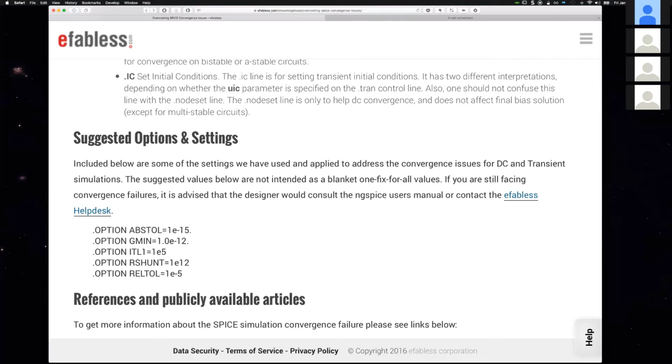If you remember, I mentioned that if you submitted it and the remote ACE was continuing to say that something was failing because it wouldn't converge, I would allow the challenge to be submitted with the error as long as you had a simulation to show that it does pass. So if you can make it pass with a particular value of reltol, then it's very easy for me to go and tweak the test bench to add that value of reltol that works. That would be my recommendation for the first attempt to get something to converge: use reltol.